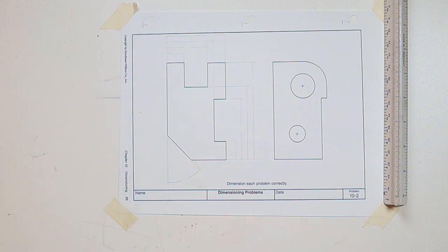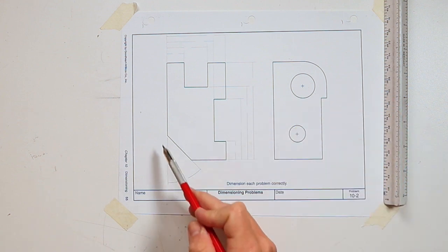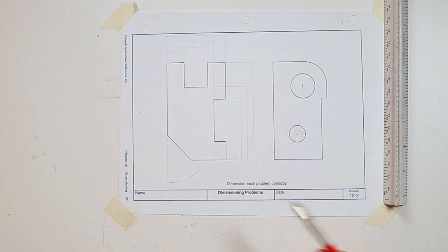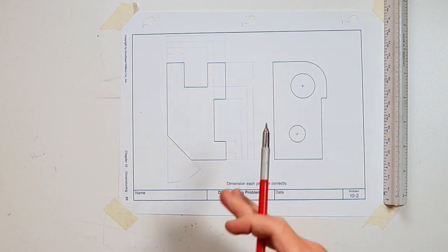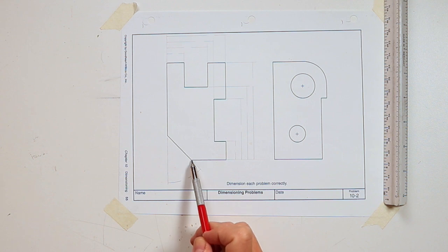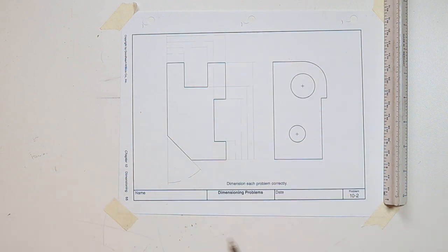So that's where my angle is going to sit. However, this is not enough information because I know the angle, but I have no idea where to place that angle. So if I were to cut this out of a block of material, I would know, okay, well, I'm going to set my cutting tool to the angle, but I don't know where to actually place the part in reference to that blade. So I need a dimension either from this side over or from the top down. I'm going to go ahead and just do the top down.